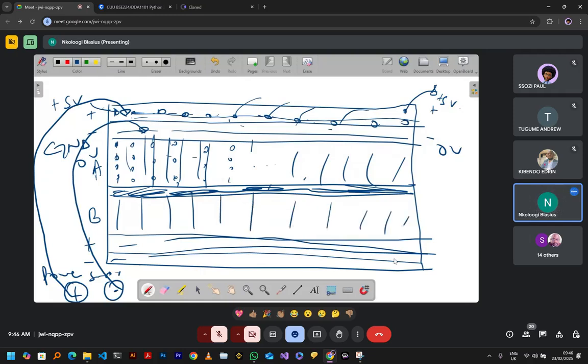So it means that if I've connected a wire from 5V here, and I connect it here, there is also 5V here. I've supplied power here, so even if I tap another wire to this point, I'm still tapping on 5V, because there is continuity vertically here.